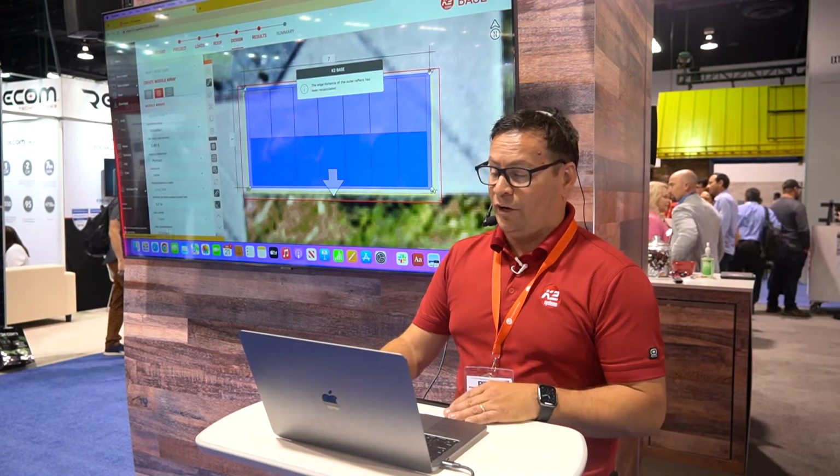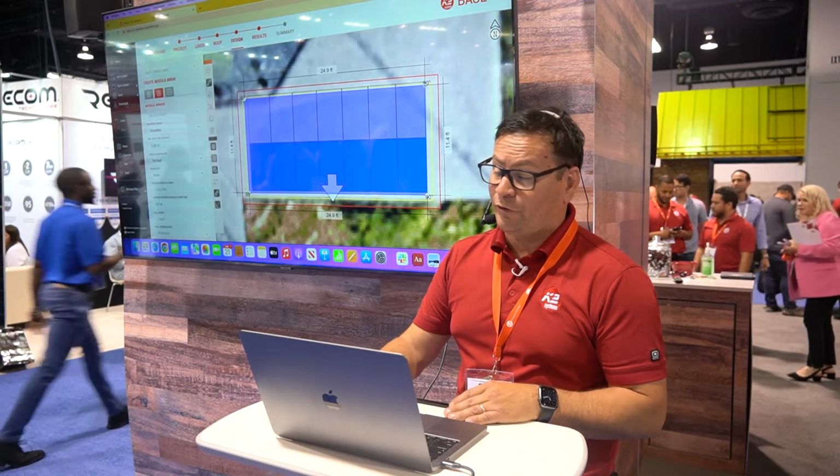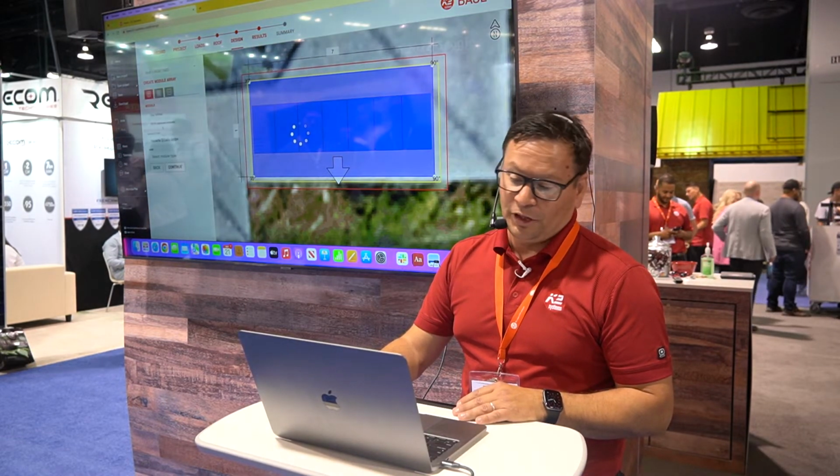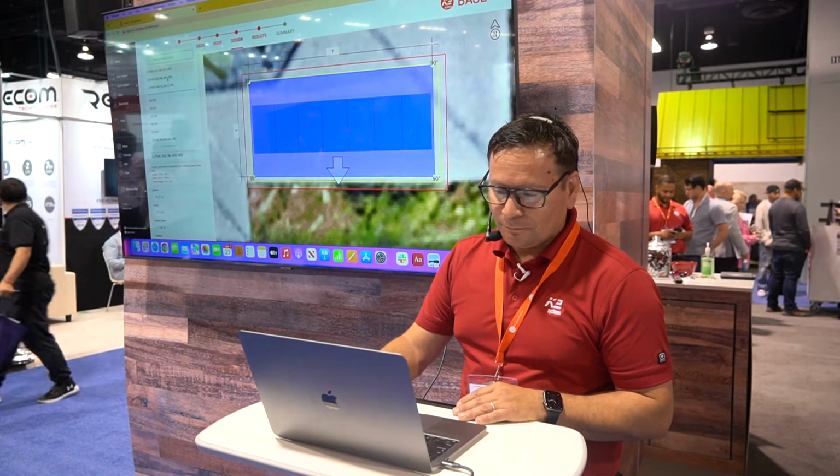What the tool allows you to do is basically make as many arrays as you'd like inside a certain area. You can resize them, you can change the orientation, anything you really wish. It's very flexible in what it's capable of doing for you. I think I picked a rather massive module, so why don't we go back to the 380. I think the 380 is a little bit more friendly for this roof. So I'll swing this on over. Looks like we got a good cluster here on the front row of the actual house.